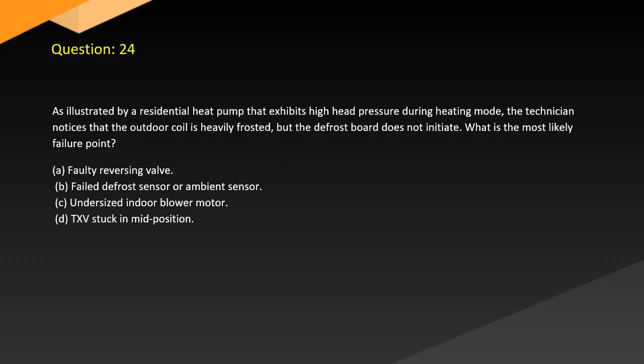Question 24. As illustrated by a residential heat pump that exhibits high head pressure during heating mode, the technician notices that the outdoor coil is heavily frosted, but the defrost board does not initiate. What is the most likely failure point? A. Faulty reversing valve. B. Failed defrost sensor or ambient sensor. C. Undersized indoor blower motor. D. TXV stuck in mid-position.